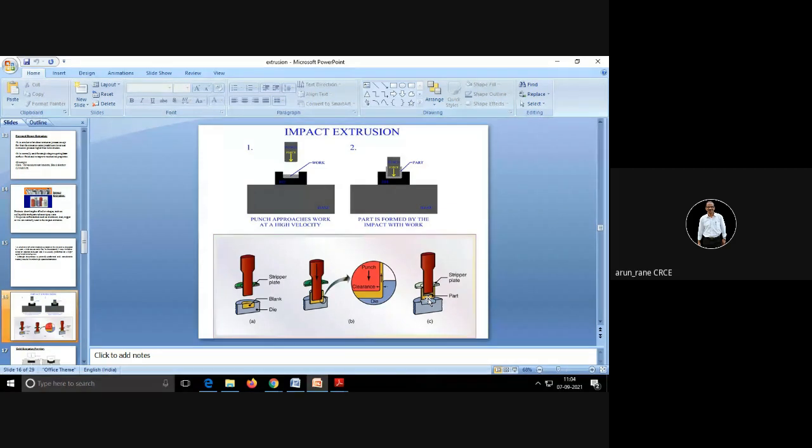So how you will achieve this? For this, you have to make punch slightly rough. Slightly rough does not mean that it will have scratches or grooves or threading kind of thing. Slightly rough, sir. Whereas cavity will be perfectly smooth, like a clean shaved face. How does a clean shaved face look? Like that, cavity will be there, so that the component doesn't stick to the cavity.